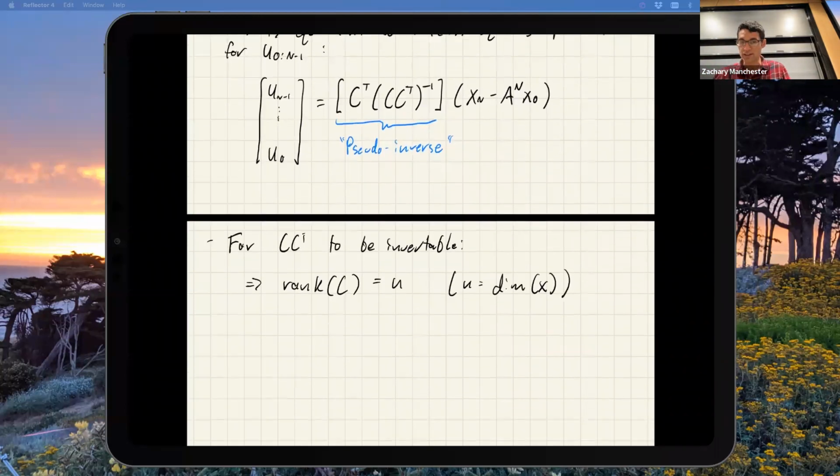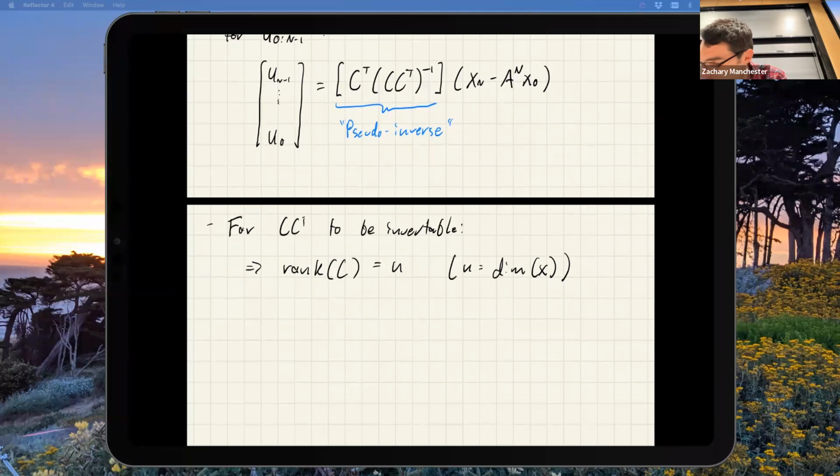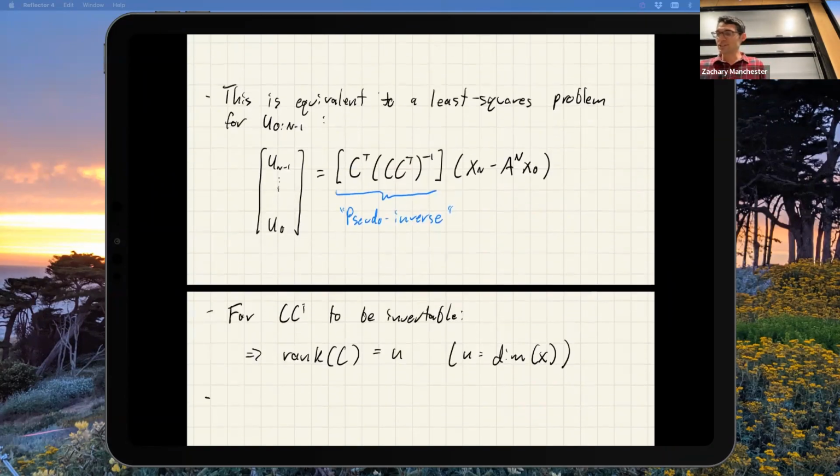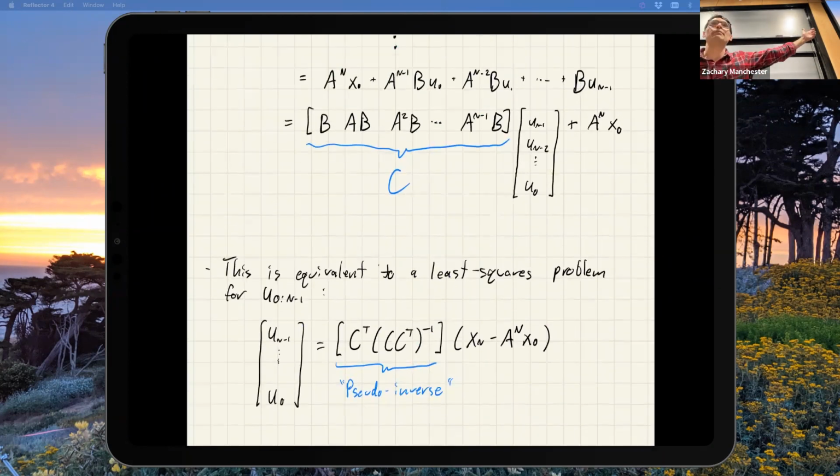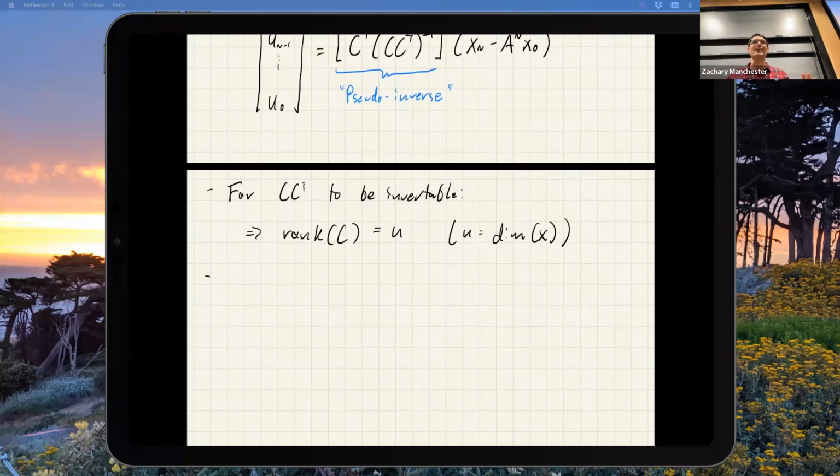Cool. Okay, so there's one last little trick that we're going to play, and this one's a little more subtle. I did this up here for some arbitrary number of time steps, some horizon big N. It turns out in the linear time invariant case, there's a specific number big N that I have to go to, and I don't have to go any higher than that. Does anyone know about this trick? Yeah. Cayley-Hamilton theorem. Who knows about that? A lot of you.